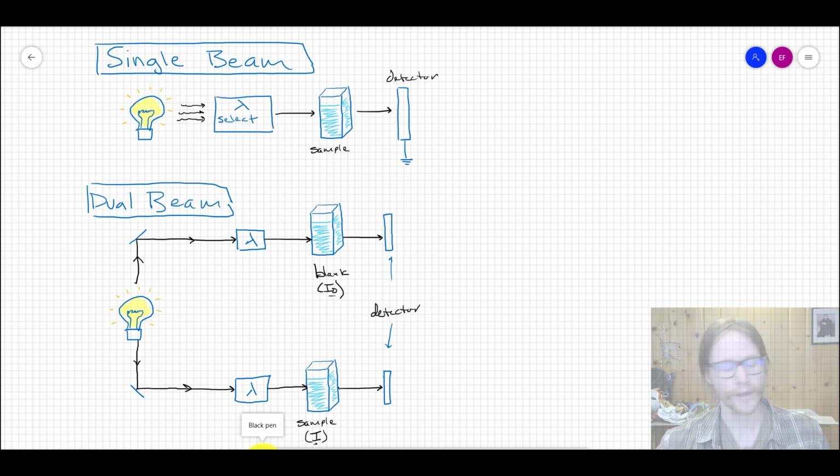At the same time, we mentioned way back in chapter 5 this thing called instrument drift, if you remember. Remember, this is just a light bulb, which takes time to warm up, and also it dies over time as the tungsten inside starts to evaporate. And so maybe you just flip the thing on right away in the morning, and then you start to measure samples right away. This thing is still coming up to heat. It may take 30 to 60 minutes to reach an equilibrium,